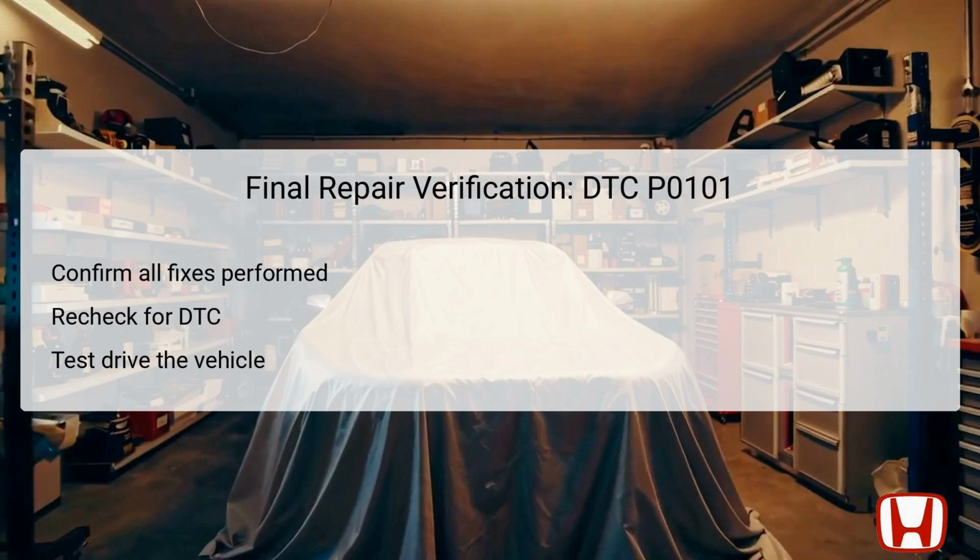It's also recommended to take the vehicle for a test drive under various conditions to check for performance issues. During the test drive, monitor the vehicle's responsiveness and fuel efficiency to gauge improvement. Ensuring that no codes return after these checks solidifies the repair work's effectiveness and confirms that the MAF sensor system is operating as it should.